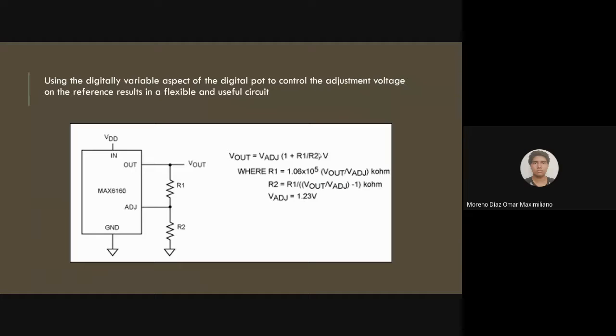The actual voltage change that occurs is known as the output voltage swing. For many op-amps, the output saturation voltages are typically the supply voltage levels minus 1 volt.